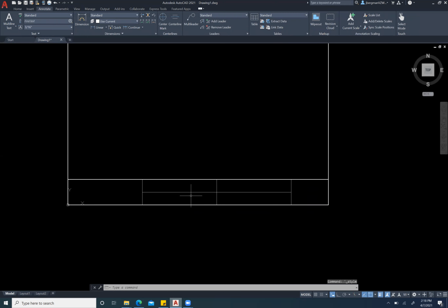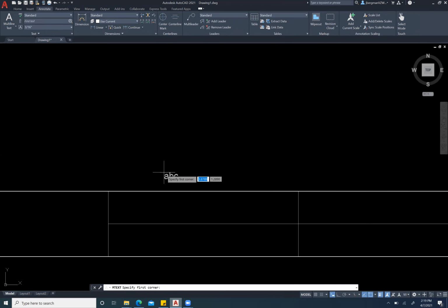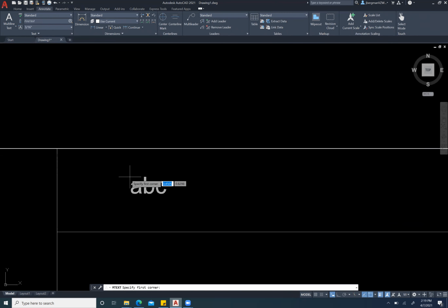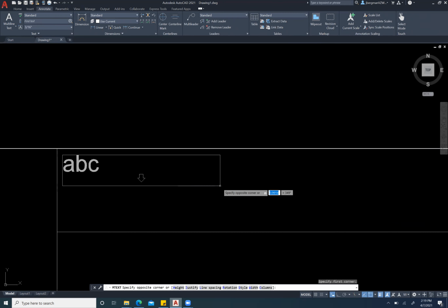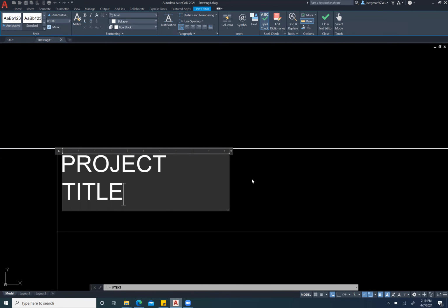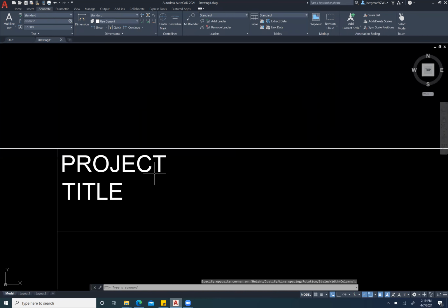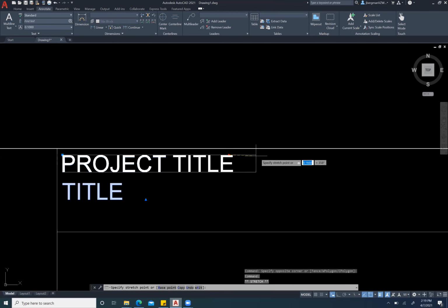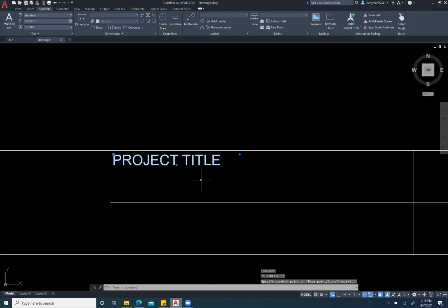All right, and then I will add multi-line text. So click multi-line text. Make sure to zoom in when you're doing this. I'm going to draw a box like this. And this first one is going to be project title, and then hit Control Enter on your keyboard to close out of that. I'm going to select this and I need to make it longer so it's on one line. To move this around, you'll click this node here, but if you want to make it longer, you just click this arrow and drag it out. And once it's the right width, just click and there you go.